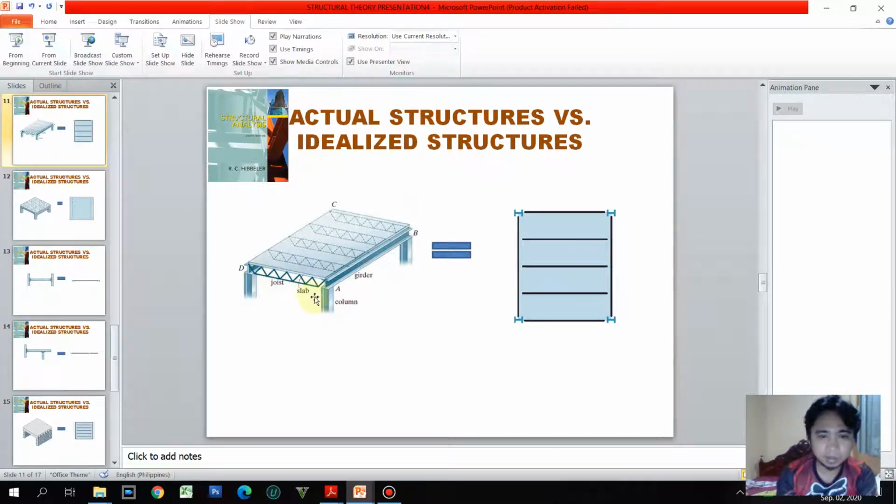Okay. Similar also to the girder and column connection, that is assumed to be a pin connection. Okay. So if it is a fully welded one, therefore we'll just extend the lines touching each other. That simply indicates that we have a fully fixed support for every connection that has a line connecting each other. Okay.